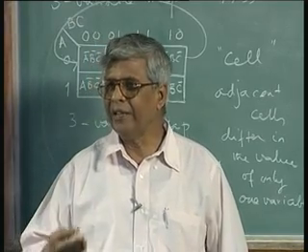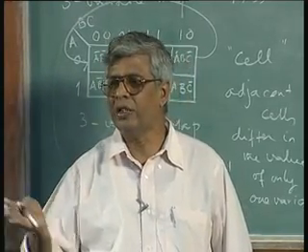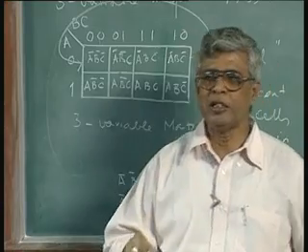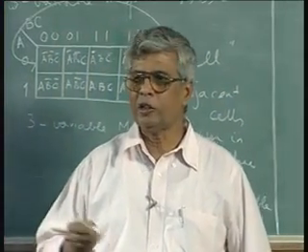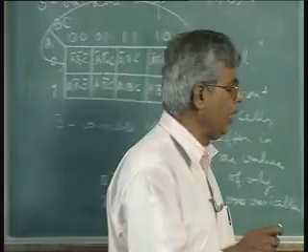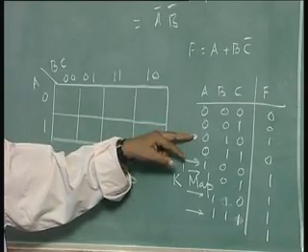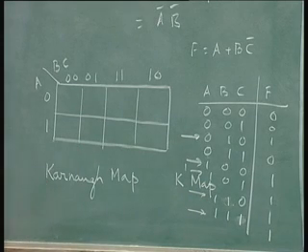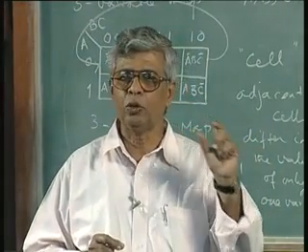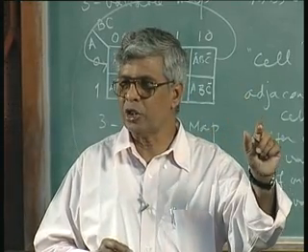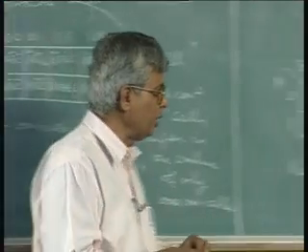Since we are going to be binary and we always have to have 0 as one of the values, in digital design, digital systems, digital representation, wherever digital things are involved, we always start with 0 and not 1. So, the first entry is always a 0 entry. So, that way I will call this 0th row, 1st row, 2nd row, 3rd row, 4th row, 5th row, 6th row, 7th row. And we also called these variations or combinations of the inputs. Each of the input combinations of a truth table is called a min term. So, the first min term is min term 0, the second min term is min term 1. As a symbol for the min term, a small m.